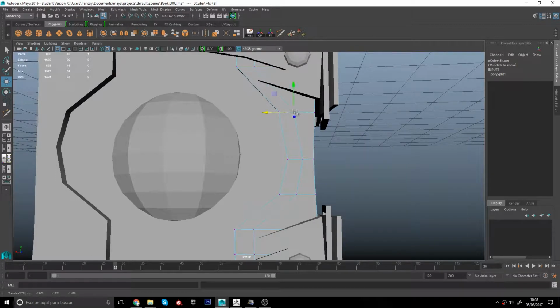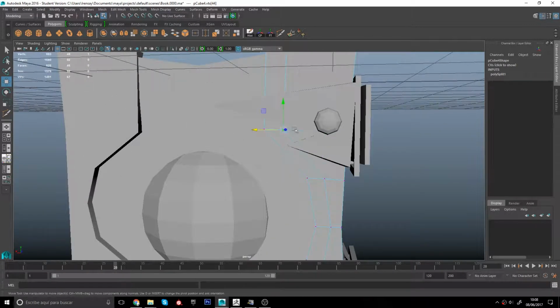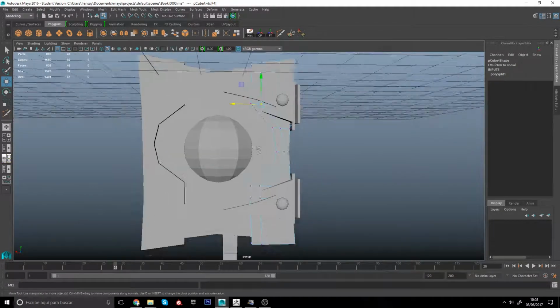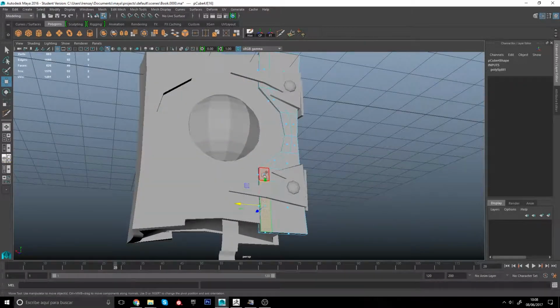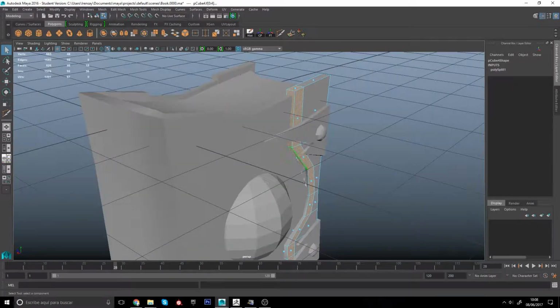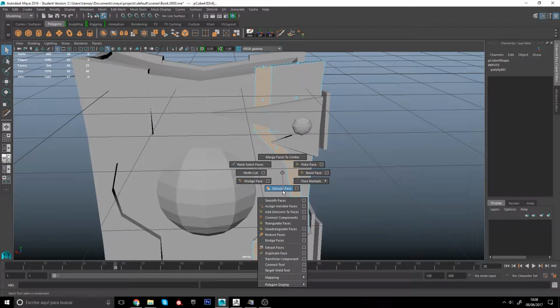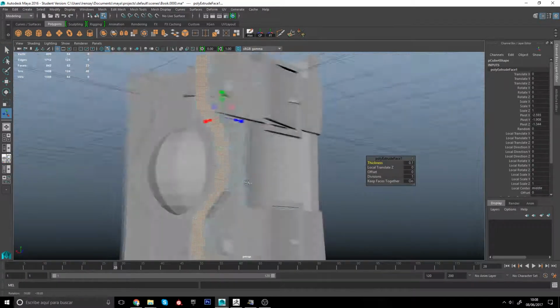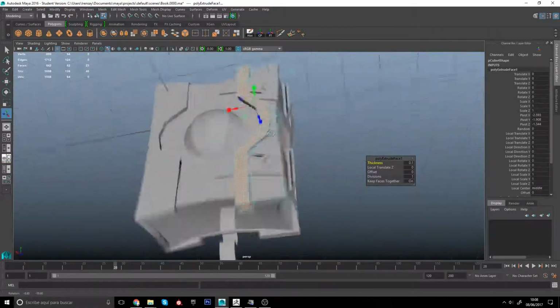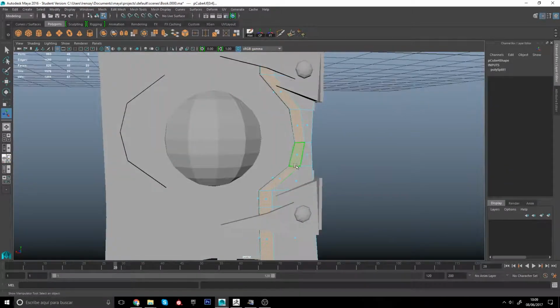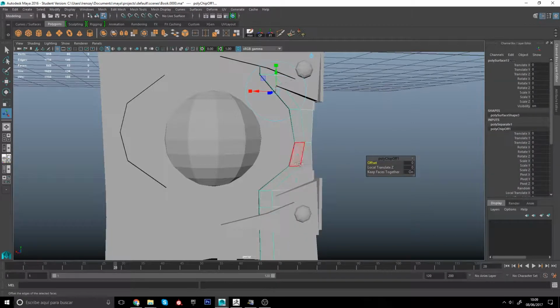Finally, we'll add some thickness to the edges of the book cover, like in the concept. How do we do that? By adding an edge loop the same size as the concept and then extruding the faces inside the loop. It's important to adjust the vertices before extruding the faces.